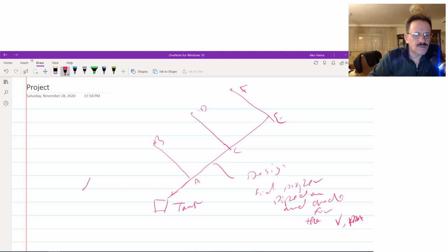It means you have to find the velocity in the pipes and check it. The velocity usually should not be less than 0.6 meter per second, and it will not be more than 1.5 meter per second.